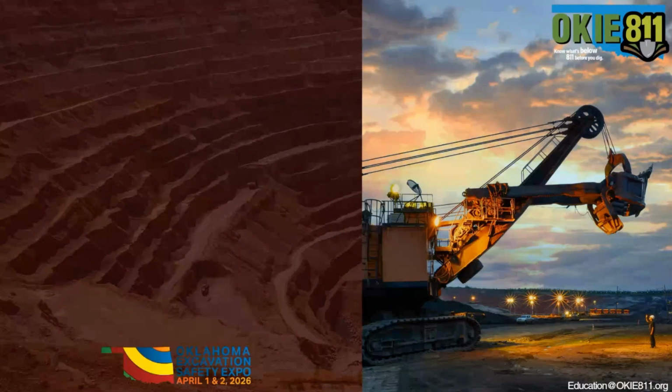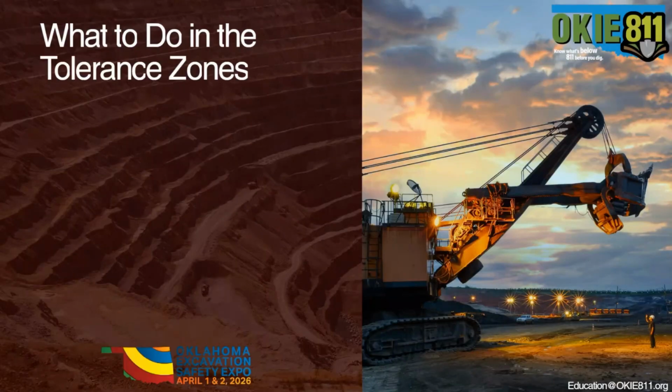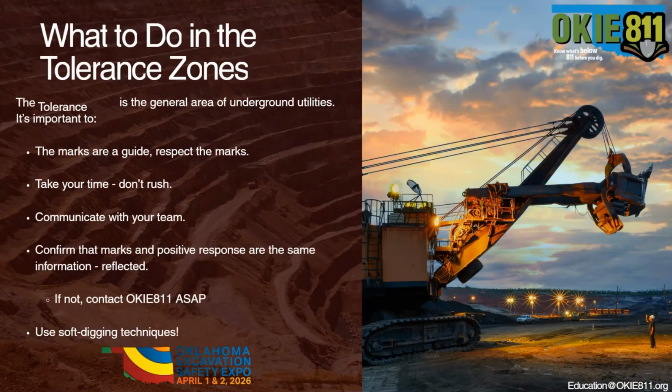So what does that look like, per se? What do we do in those tolerance zones? What are those rules? Again, remember that the marks are a guide. It's not an answer. Respect the given area of the markings, the 24 inches, 2 feet each side, and use that as your guide. Respect those marks if you need to work around those utilities.